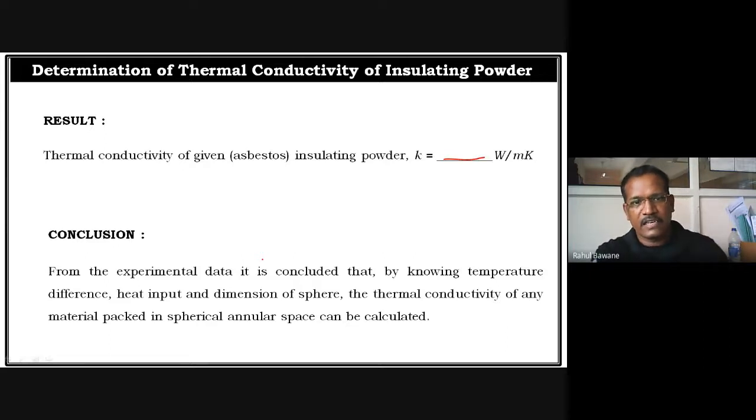After conducting this experiment, what is the conclusion? From the experimental data, it is concluded that by knowing the temperature difference, heat input and dimensions of the sphere, the thermal conductivity of any material packed in a spherical annular space can be calculated.